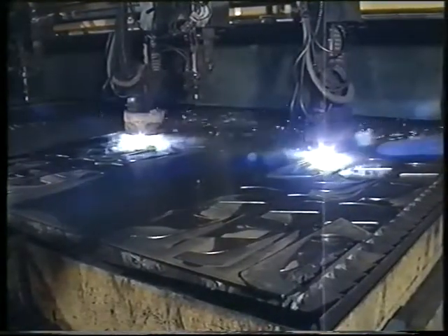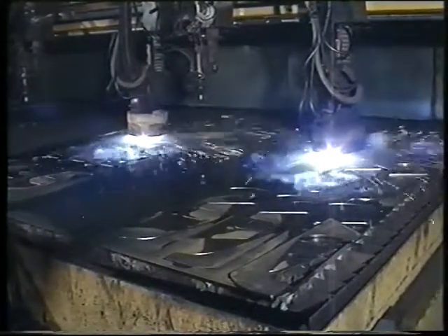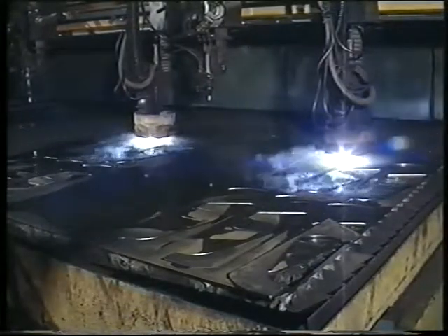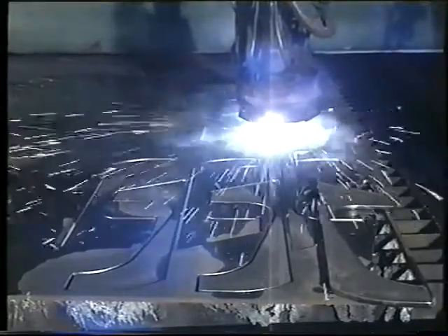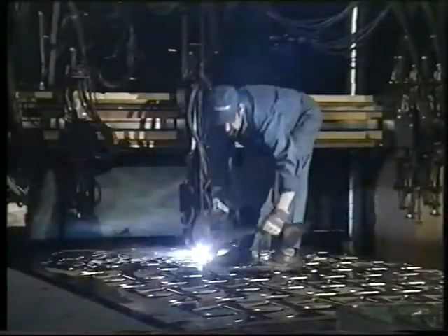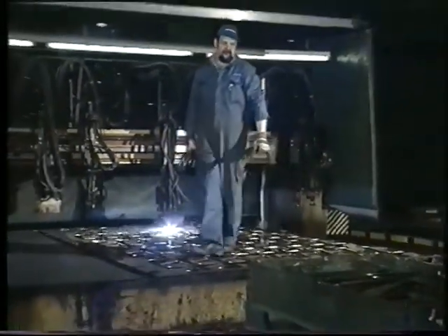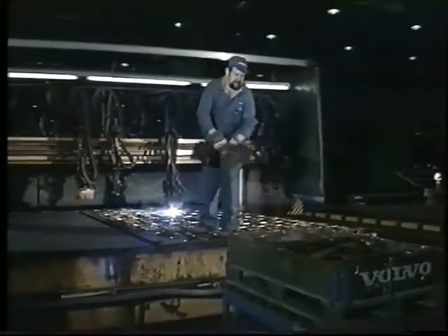Normally, 3 plates are cut simultaneously. By placing 2 plates lengthwise, however, it's possible to increase machine utilization. Only structural steel is used. All told, a total of 400,000 meters are cut per year using both plasma and flame cutting. The same number of piercings are also performed.